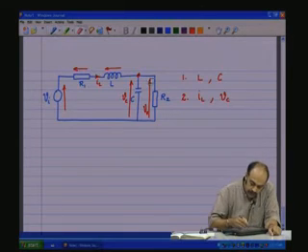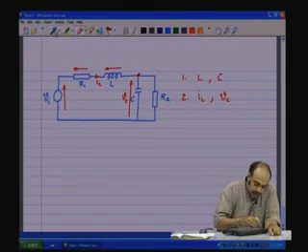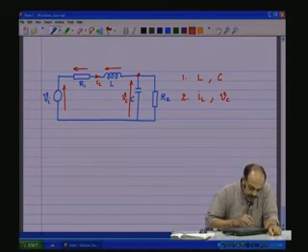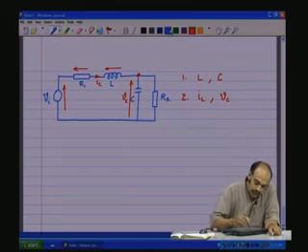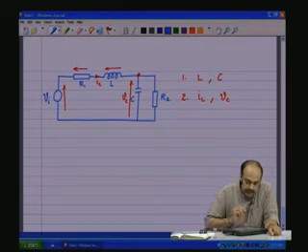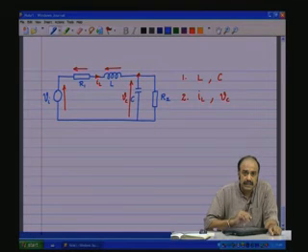But on the circuit, we just keep only those variables which we need to form the equation, which are the input variable Vi, the state variable Vc, the state variable IL, and the parameters of the circuit R1, L, C and R2. Okay. These are the only variables that need to be written down on the circuit, and the whole dynamic behavior of the circuit should be formulated with just these variables, nothing more, nothing less.